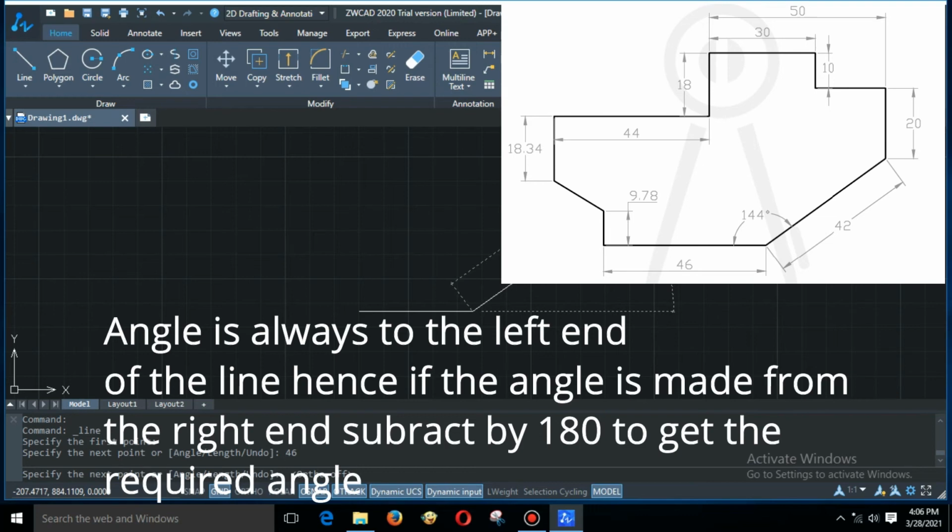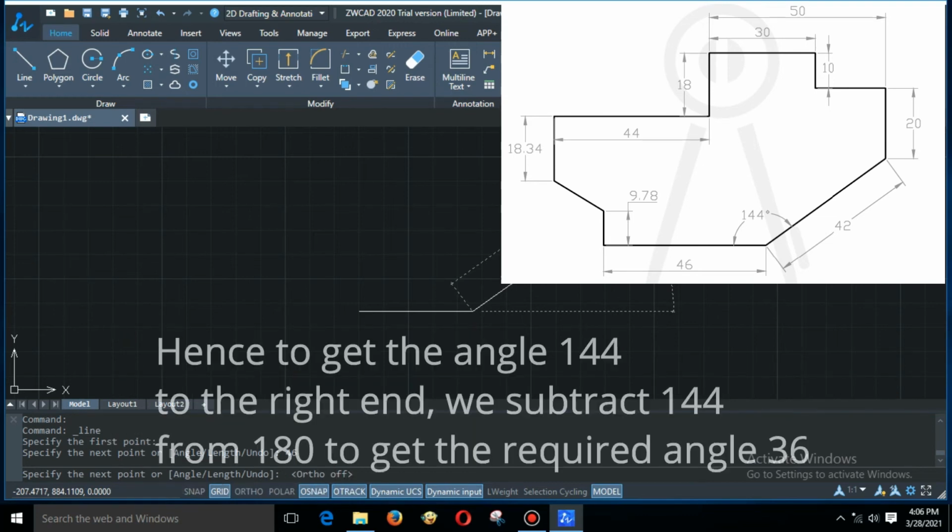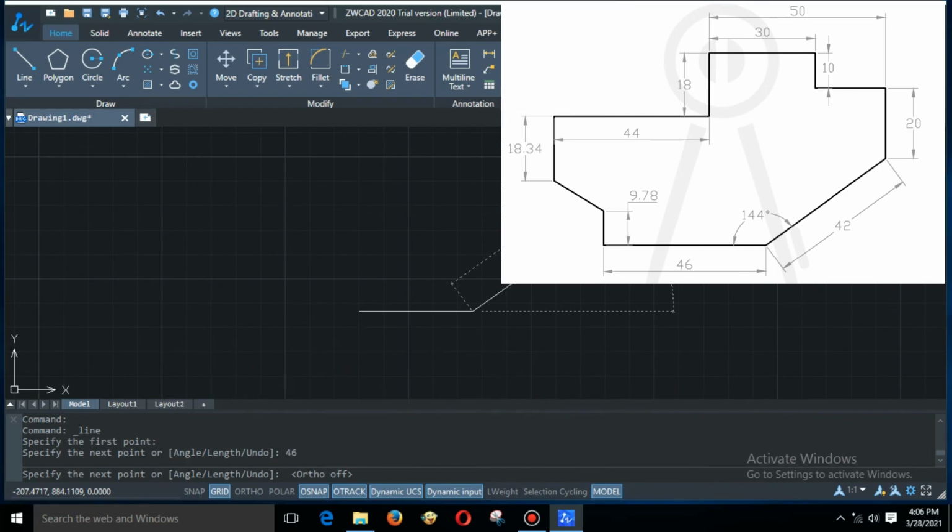First of all, in the block which is written 81.6796 is the dimension. So we'll put in our dimensions there. There's no change in dimension. We use tab, and the angle should be 36, because 180 minus 144 is 36, and we want this type of angle, so we'll add in 36. That is the line which we wanted to draw. Now we'll add again F8. F8 is for ortho, that is 20.